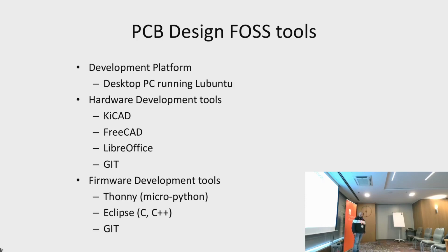If the PCB has an MCU on board, a microcontroller, I use Eclipse if the firmware has to be written in C or C++. And since a few years, I can program the microcontroller in Python, and for that I use Thonny. It's an open source IDE for Python and works really well with the microcontrollers that support MicroPython. And again, Git for version control of the software.